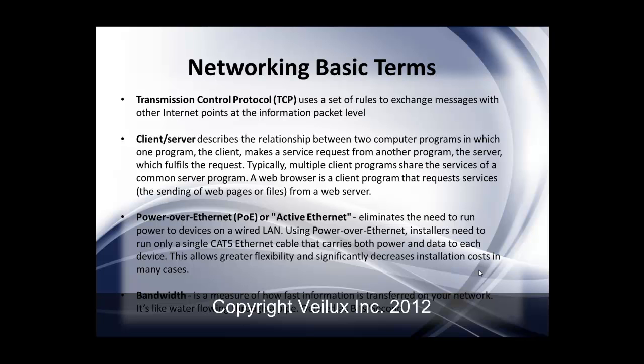Power over Ethernet or active Ethernet eliminates the need to run power to devices on a wired LAN. Using power over Ethernet, installers need to run only a single Cat5 Ethernet cable that carries both power and data to each device. This allows greater flexibility and significantly decreases installation costs in many cases.